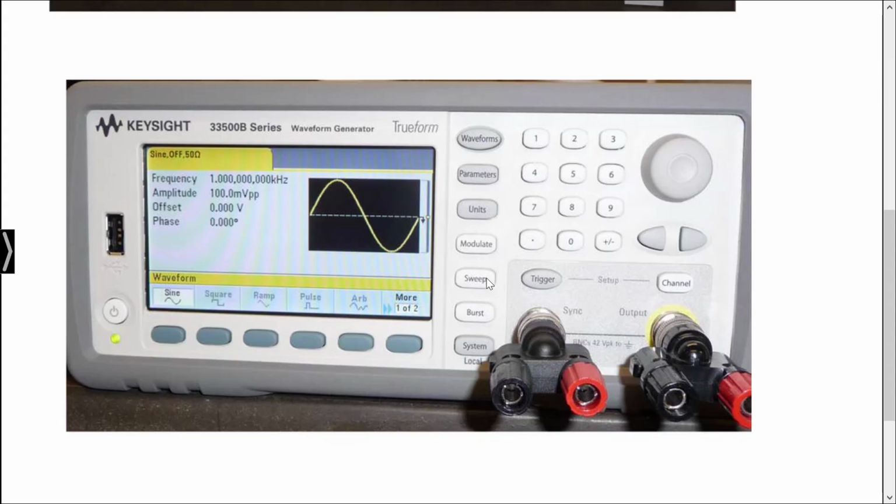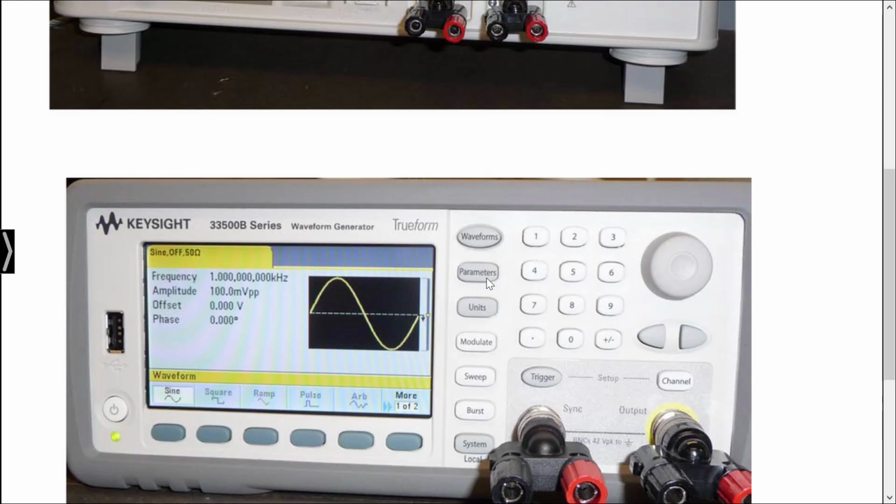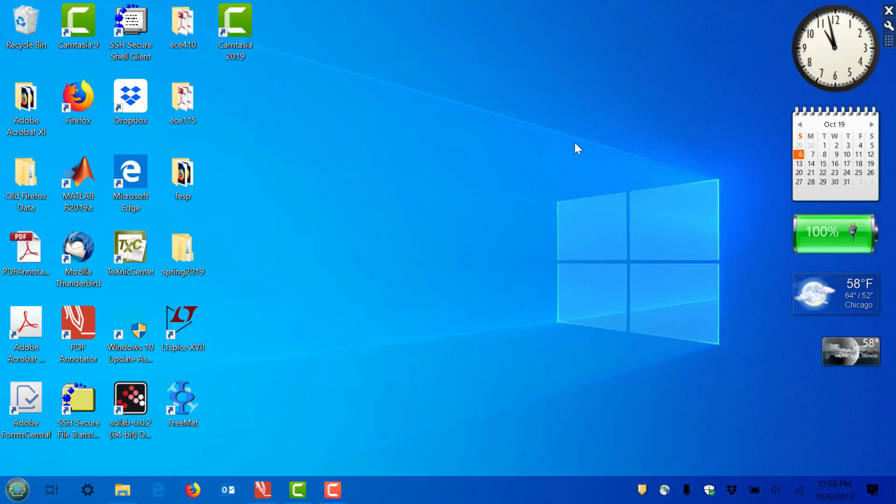So anyway, these are the two pieces of equipment that you will use, and you will be asked to set up a very simple circuit and analyze it. There's actually 3 different circuits that you will analyze. So to that end, let's take a look at those circuits on the simulation, because on the simulation this time, we'll be actually using a different mode of the simulator. So far we've used constant inputs, using the power supply, but now we're going to apply a sine wave. So with the sine wave, we will run what's called a transient analysis in the simulator. Transient analysis, also called time analysis.